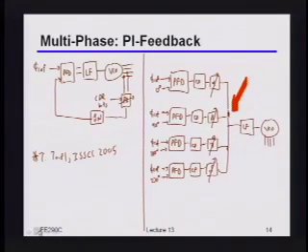By the way, I should also mention this was done by some folks from Rambus. It was first published in ISSCC, but the journal paper is from John Poulton, in JSSC, December 2007. This was for one of their first low power link kinds of things. There are lots of different potential ways to do these things, but the ones we've been talking about the last couple of slides are really nice when you have these heavily multiplexed systems where you need to generate multiple clock phases all with the same controllable phase offset.